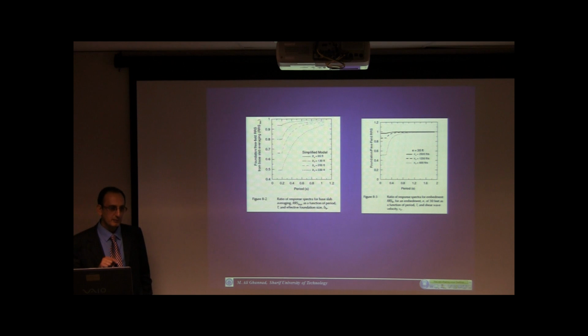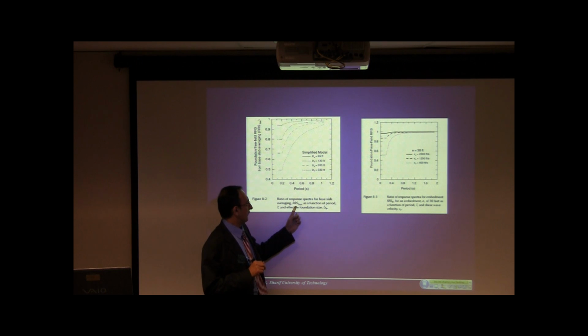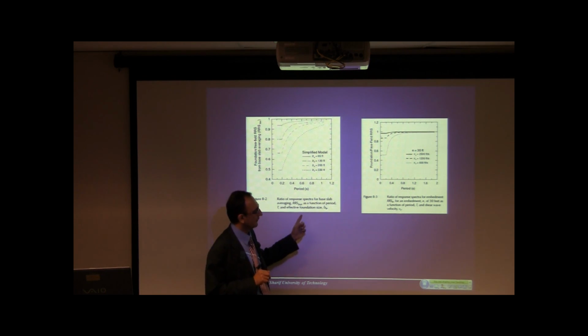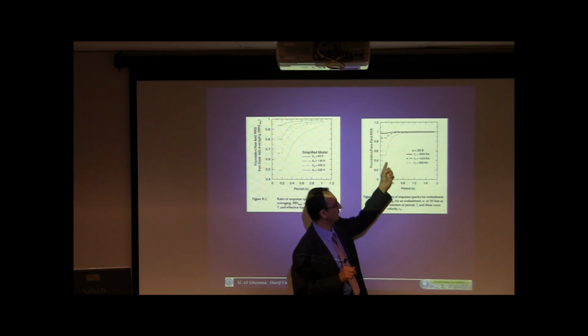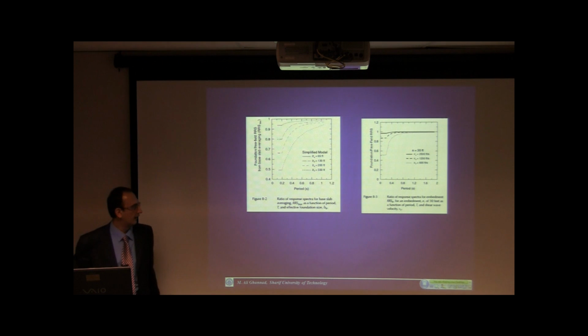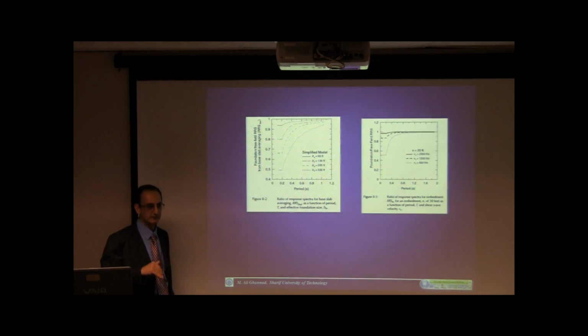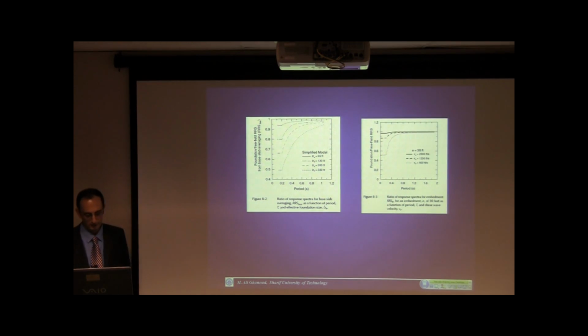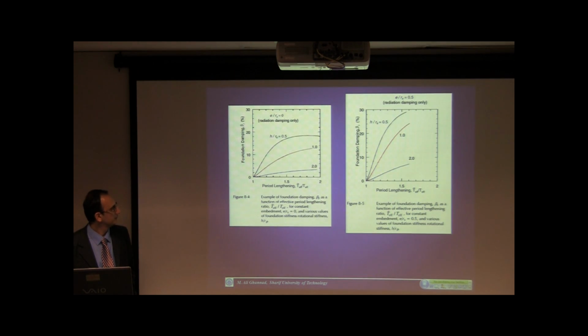But for kinematic interaction, they just consider the effect of base slab averaging, and also the effect of embedment ratios. They are all reduction factors, and the idea is that kinematic interaction always reduces the input motion relative to the demands of the soil structure system. We will talk about it a bit later.